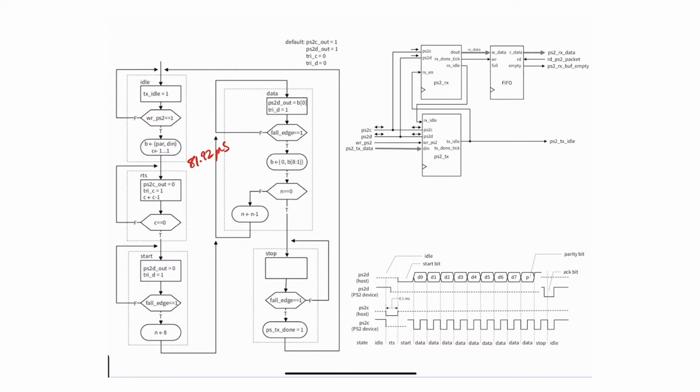Anyhow, before I jump into the rest of the system, I just want to emphasize that when we look at the implementation, there's another state inserted that is actually not shown on this diagram, and that's why I'm not showing it on the finite state machine either. Its purpose is just to make sure that the RX is idle. So the state is going to be called wait for Rx, or wait R. That means wait till the Rx is idle.